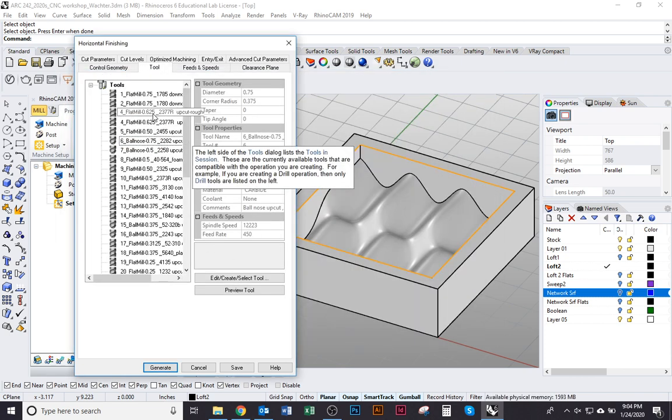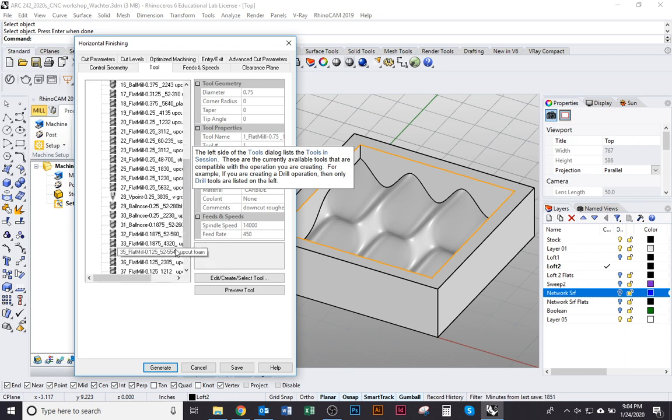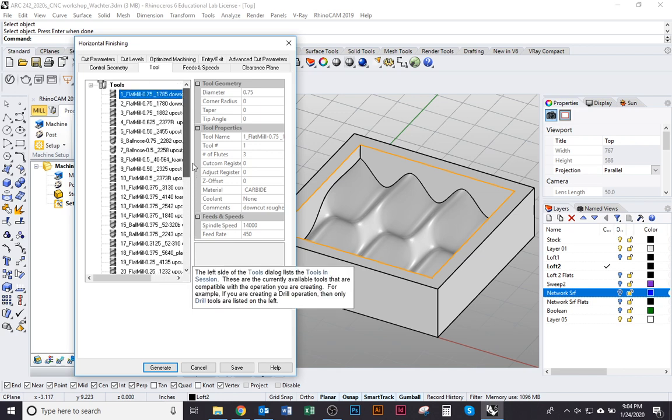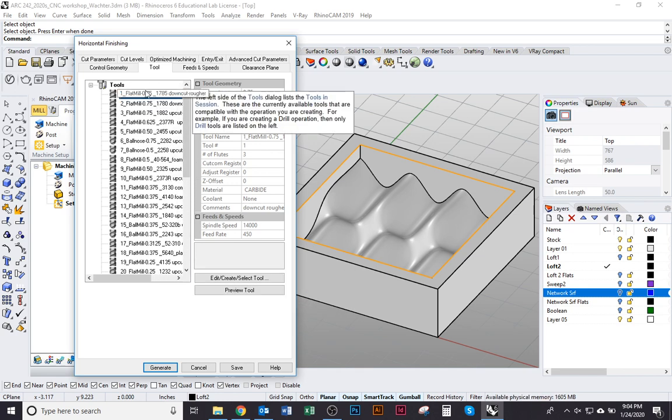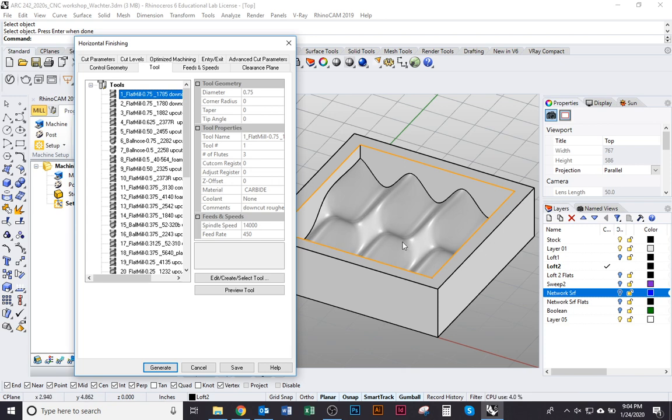Okay. The next bit of information over is the diameter of the bit. We have everything from a 3/4 inch bit down to a 1/4 inch bit, even an 1/8 inch. And so generally speaking, the larger bits, the ones we'll use for roughing. What roughing is just removing material. So if you're working in something harder than foam, which is what we're working with now, you'd want to do a roughing pass to kind of remove the material relatively quick with a bigger bit, and then go in with a smaller bit and get more detail and going closer.